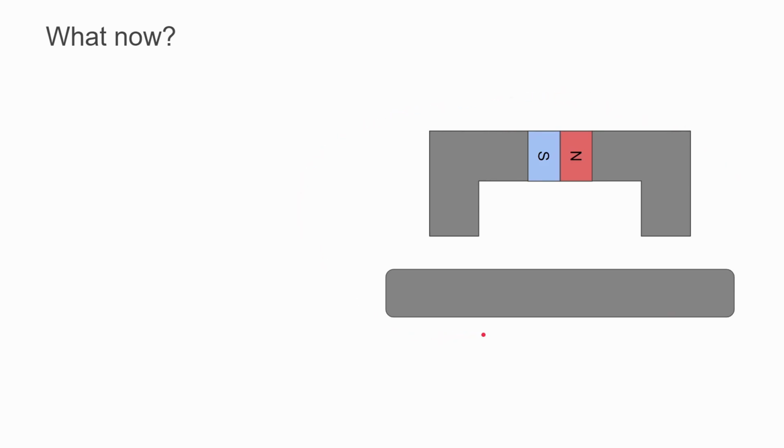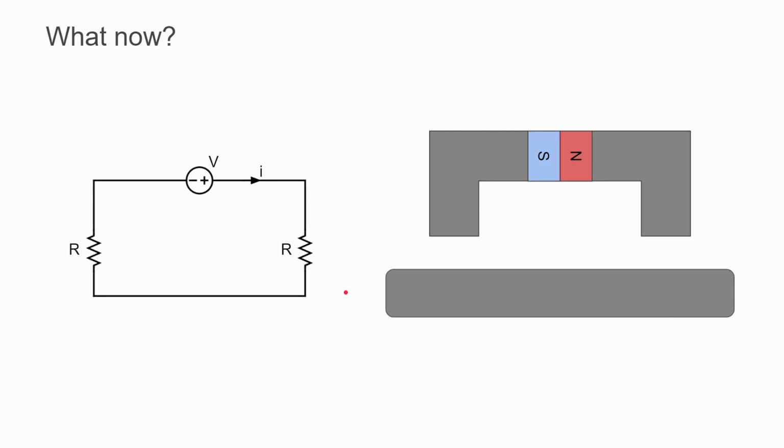We could represent it with an equivalent electric system drawn like this, where the resistance is due to the air gaps because steel has pretty low resistance for the most part. This calculation process uses essentially electric circuit formulas to calculate the current or flux going through the system. Once we know the circuit flux, we can look at the total amount of flux in the air gaps to calculate the lifting force on the bottom beam here. This is actually very simple. All the calculations are just slightly modified from what you'd do for a normal electric circuit, given some of the principles that we've already talked about.